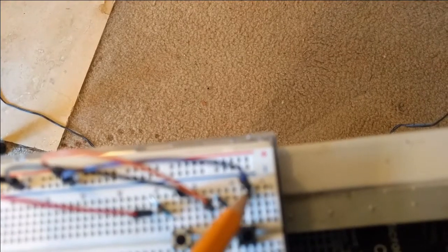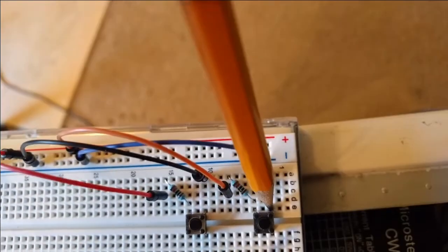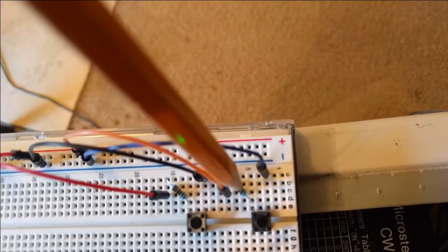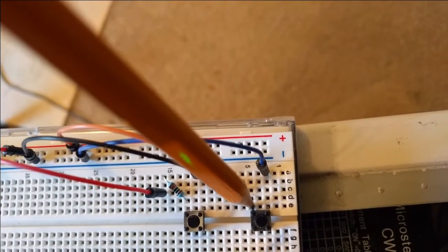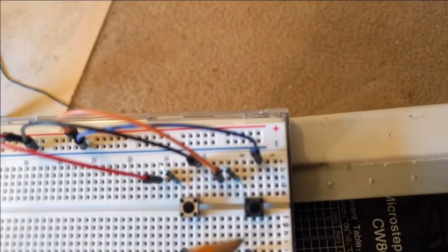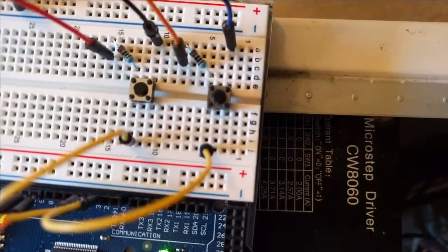On a breadboard, all these are connected in that line. So if I plug in this here, it is connected to this prong on a button, my 10K resistor, and that's connected to that prong of the button. And then this lead is connected to this yellow wire going to pin number 2.